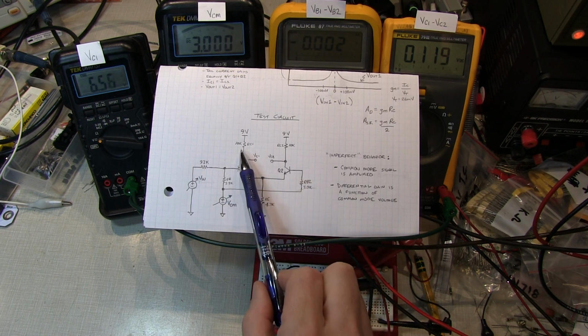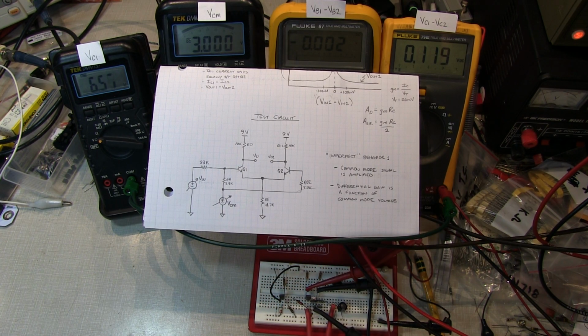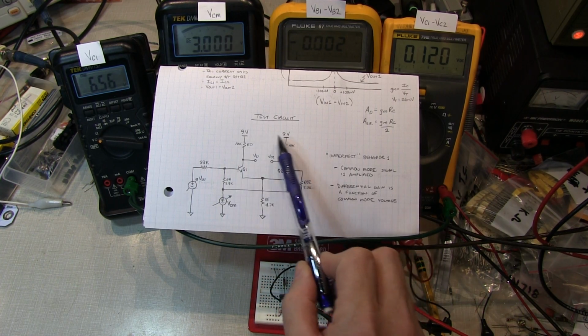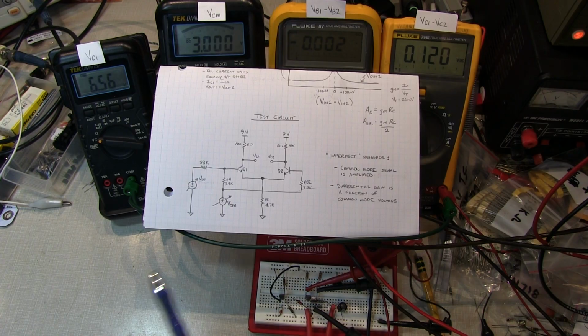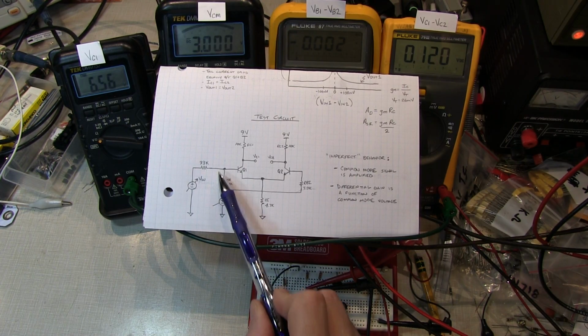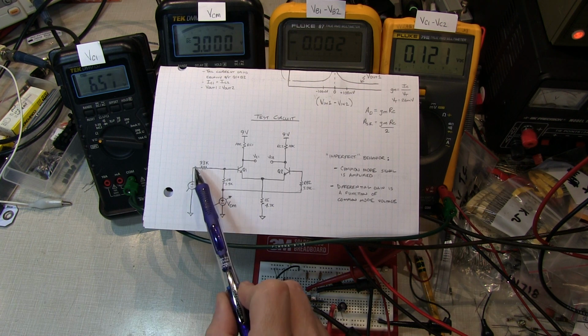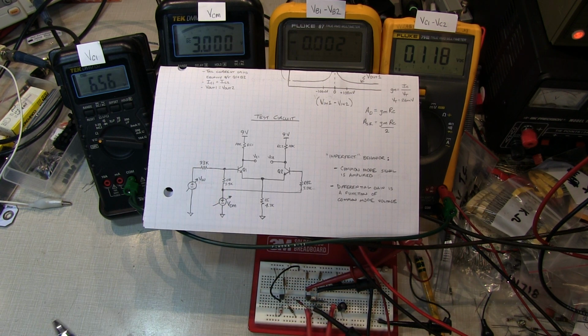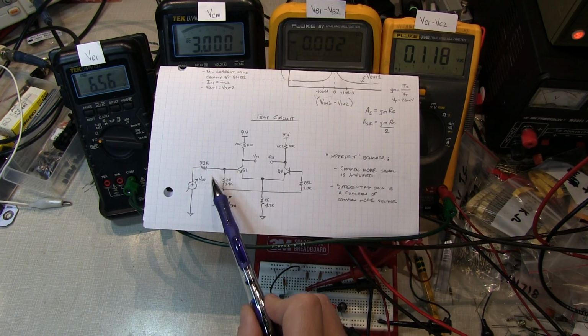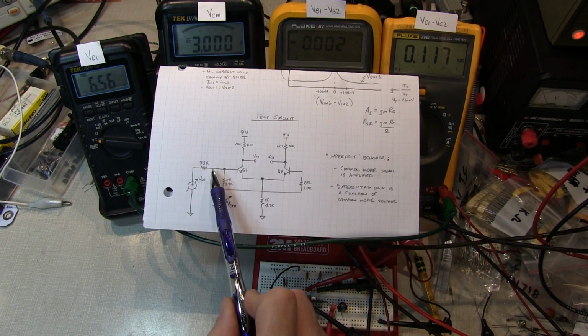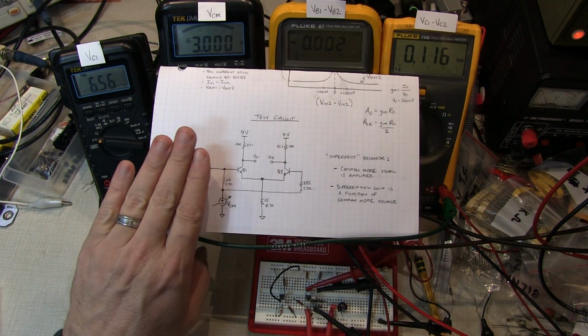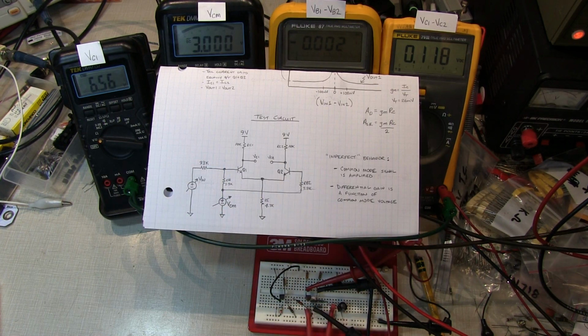I've got a pair of 10K resistors as our collector load resistors, and I'm using a 4.7K resistor as our tail resistor to create the tail current. And I've got a 9-volt power supply to bias the whole circuit up. I've got another variable power supply that's feeding both bases through 3.9K ohm resistors. And then I've also got this 33K resistor hooked up to another variable supply that I can use to vary this voltage with respect to that one. Right now I've got that disconnected. It's not in the circuit right now. So all we have is that part of this circuit to show what's going on.